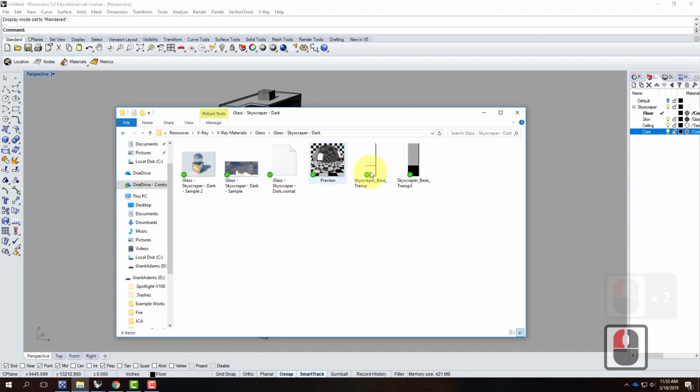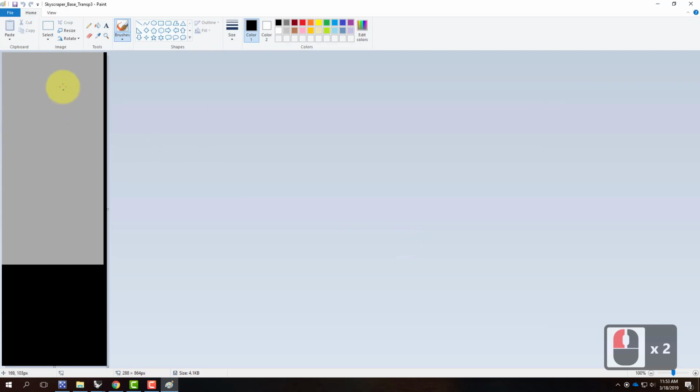Part of it is the reflection, but there is also a transparency gradient that's been established for you. This is the one that's actually used, where it's semi-transparent in the upper part of the panel, but the lower part of the panel isn't. That would be where the floor would occur, where we have the space in between the floors. So we need to make sure that we texture map it so that we're seeing all of that correctly. Likewise, the width here is meant to be about the size of a glass panel, so about 4 feet wide.